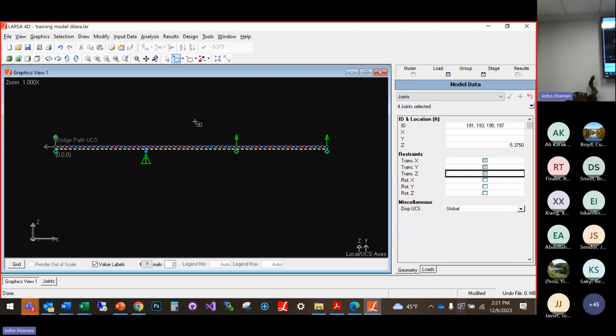When you click view, you don't see anything changing in complete rendering. You will see something change in single rendering. But we need complete rendering now to see the girders clearly. So we unselected all. Now take this selection. You can select this girder, this one.